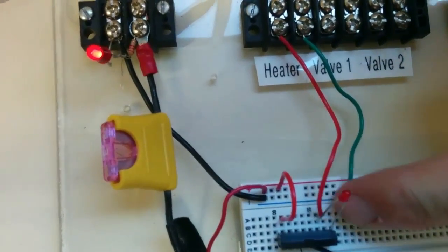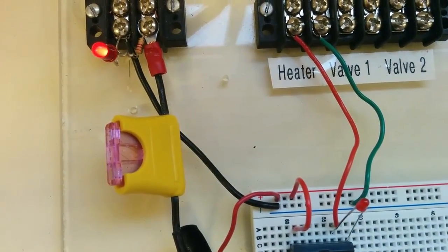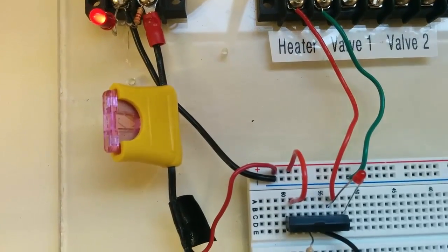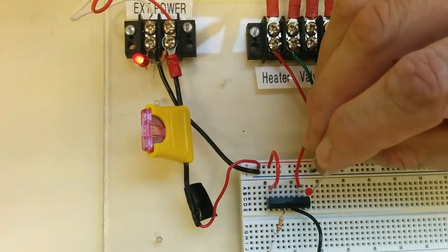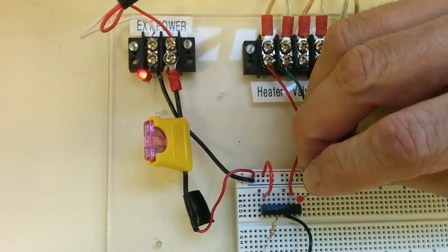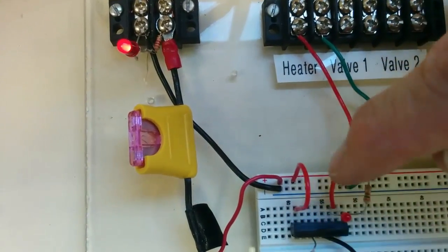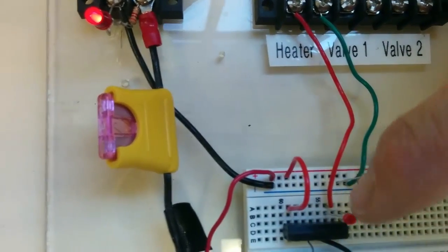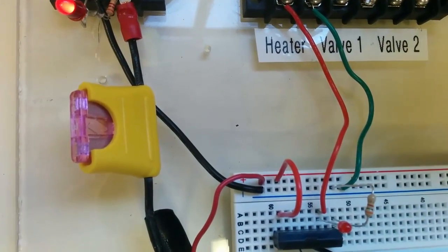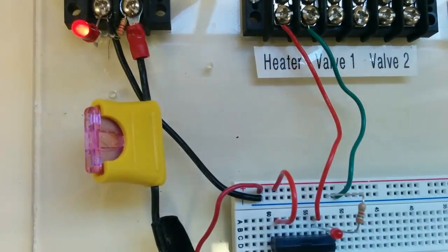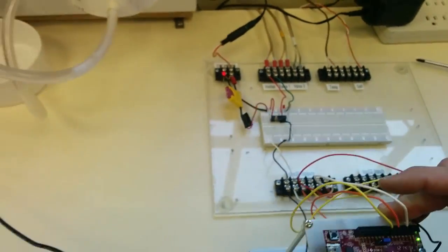So we went from the positive over a couple of columns, and now we have to go through a resistor. Remember, this is another resistor you guys have to choose. And from there, we need to go to ground. And so I'm going to bend that up a little bit, insert it in ground, and in that same place. So now we've got the LED from 12 volts after it's switched, through the LED, through a resistor to protect it, down to ground. So now we should be able to power this up and watch the lamp come on and indicate that things are up and working.